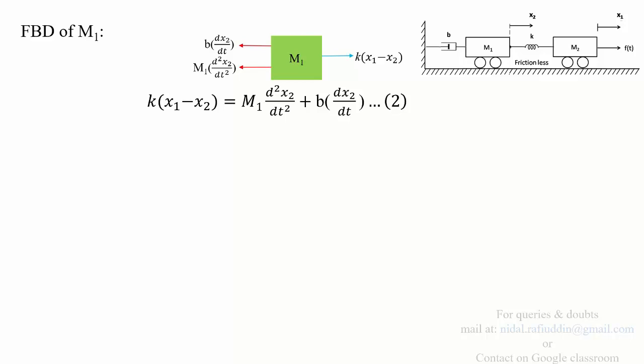So for this particular case, most of the books adhere to the concept of assuming displacement and velocity as the state variables for a mass, and thus since the system has two masses, we'll be assuming that it has four state variables. And this is also justified by the two differential equations of second order, which get converted into four differential equations of first order.